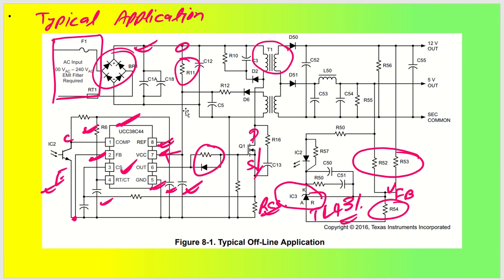So this was all about a complete design where we have seen each and every parameter, like how to power supply the VCC pin, how my output pin is driving the gate of the MOSFET through an RD snubber to reduce the ringing effect, okay. Then we have the grounding, then we have the RT and CT pin to set the oscillator switching frequency, okay. So RT CT pin we have done.